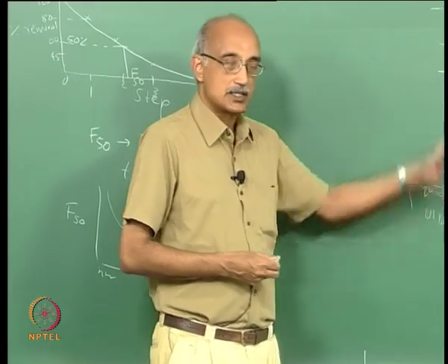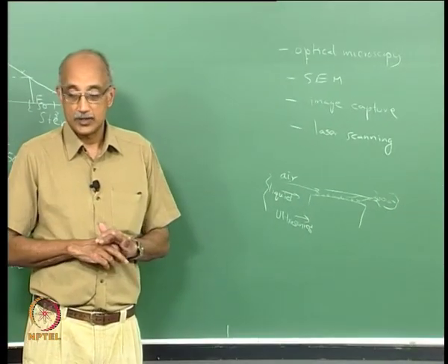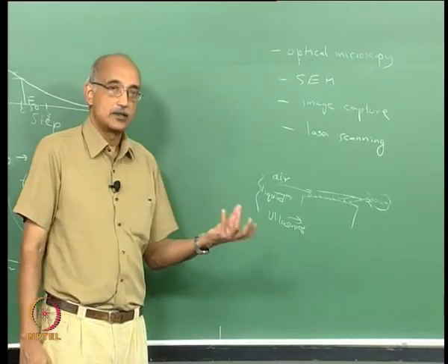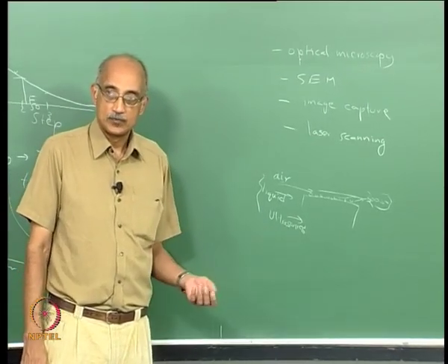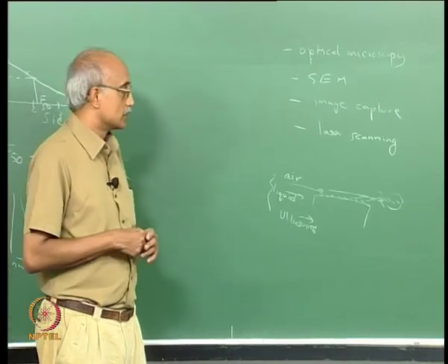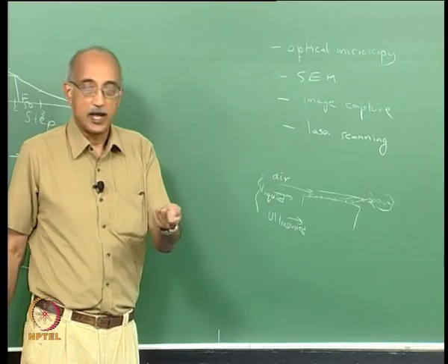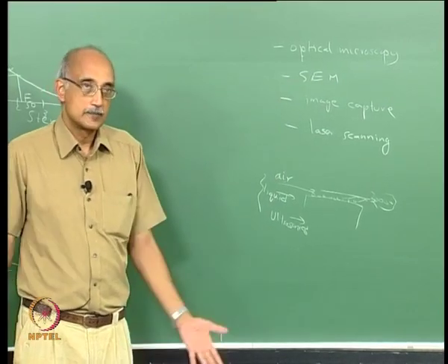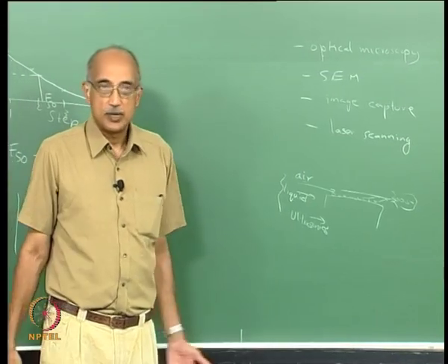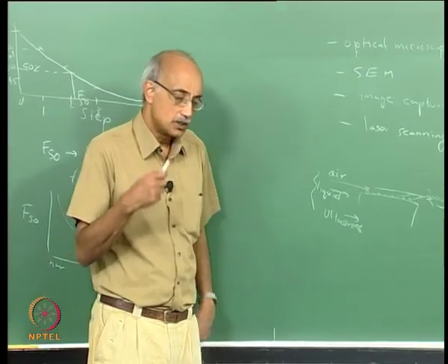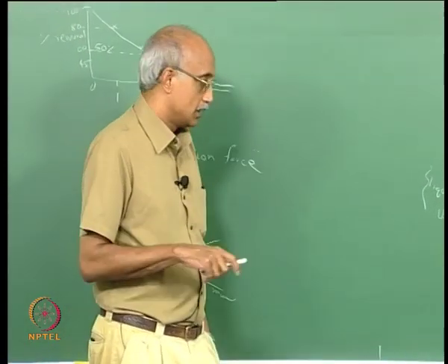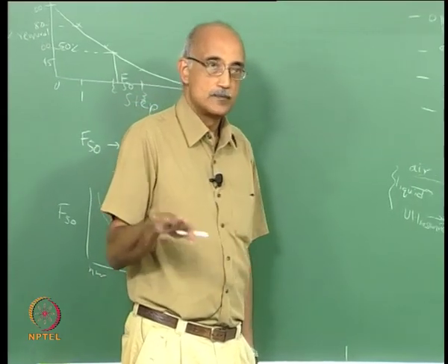If you are going to be using a scanning electron microscope to identify whether or not there are particles on a surface, then you have to use a very aggressive cleaning process like ultrasonics in order to get the surface to be clean enough for SEM inspection. On the other hand, if you are just going to do a magnifying lens or naked eye inspection, then just doing some air blow off or wiping or vacuuming may be sufficient. So these are all considerations that you have to take into account when designing a process to remove particles from a surface.